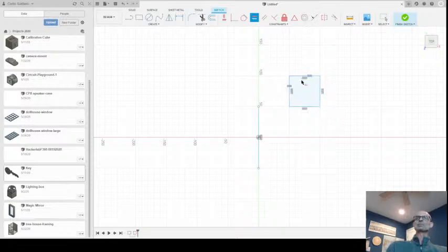Yes, it only lets me do two. Alright, so let's see the effect that has on the sketch. I can still move it around and I can scale it around. So now let's see if this side is equal to this side. This has to be vertical, these have to be vertical, these two have to be horizontal. Then how else can I constrain this?